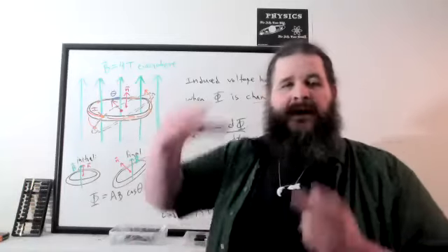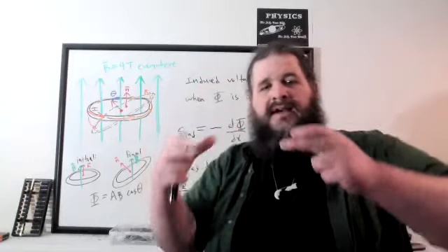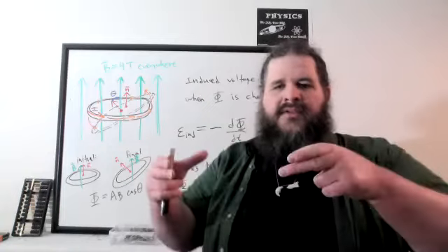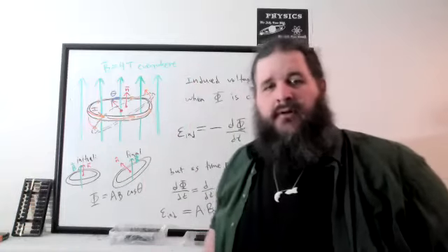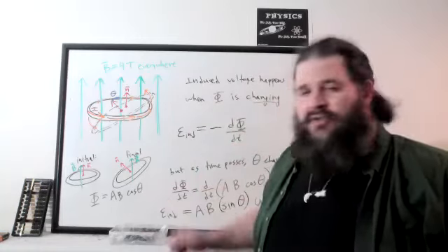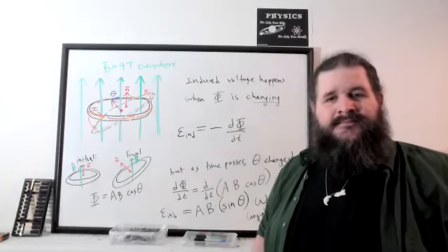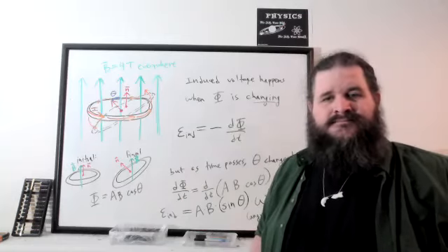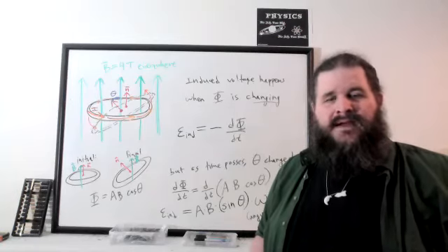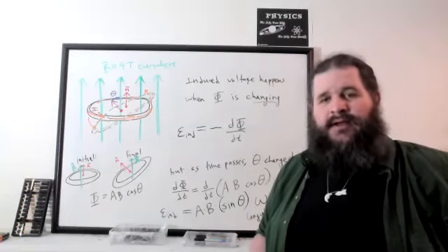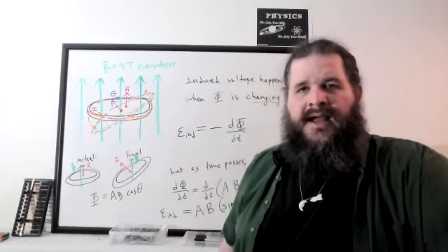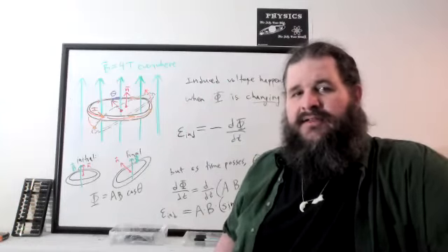If you want current flowing the other direction, you'd have to start at some other angle and rotate approaching that horizontal. In a full rotation, the problem is that it flips the normal vector around. So at that point, you would basically have to treat the angle as 180 degrees. And what's cosine of 180 degrees? Yeah, cosine of 180 degrees becomes -1. So when the angle goes to more than 90 degrees, you get a negative value for flux. And at that point, whether it's increasing or decreasing becomes really confusing.